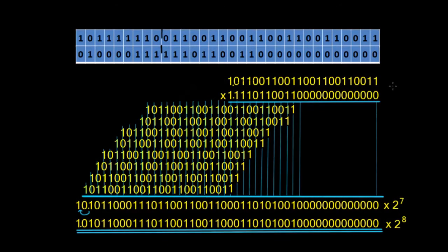We're at this point here where we've got a 24-bit number, and we're multiplying it together with another 24-bit number. Whenever we multiply these two together, we're going to get a 48-bit number, so that's just 24 plus the 24. And the decimal point is going to be this number of places to the left.